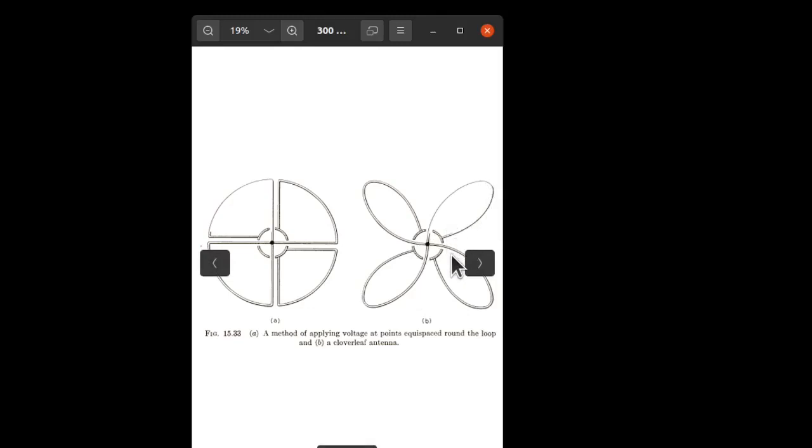These shorten the length of the wire. That's, well, not strictly speaking shortening the length, but certainly gives us a constant current over these lobes, which give us the omnidirectional antenna pattern that we seek from a loop. You might see some of these in modern constructions. We'll get into those later, but this is the historical perspective.